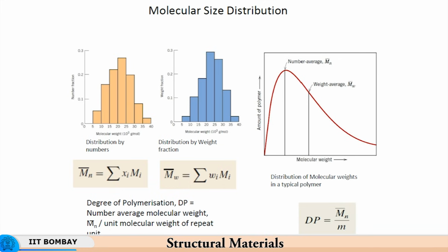So there is a significant difference between how metal properties are derived and how polymer properties are derived. Metallic properties are derived based on interatomic attraction, interatomic forces, whereas polymer properties are derived from molecular level attraction or molecular level phenomena to a large extent. So, if you look at the melting point, for example, again with a different molecular size distribution, you will have a different melting point.